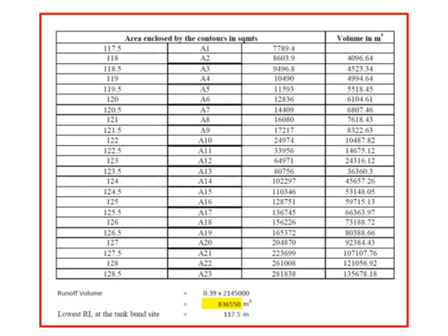and we know the catchment area. This catchment area is not the sum total of these areas. It is the area that has been got from the topo sheet. So you have to mark the ridge line on a topo sheet and then determine the area using the planimeter. This is the area that we got, which we measured using the planimeter, and that is particularly got from the topo sheet. So taking the catchment area and multiplying by the runoff depth, we get the runoff volume.